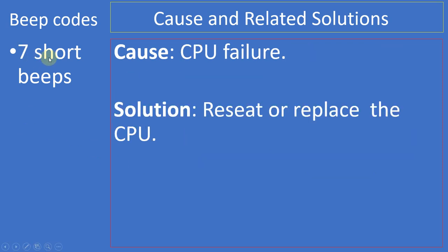So 7 short beeps, the cause is CPU failure. The solution is to reset or replace the CPU. This 7 short beeps, I myself face this problem in most Dell laptops. So the cause of this is probably CPU failure.